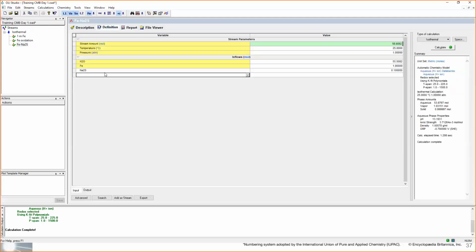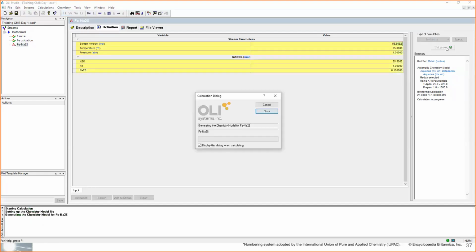So what about if we turn on the oxidation state for sulfur, all of them? What happens? What can happen? So we go to the redox, and then we click on this drop-down arrow, and we click on sulfur. Just enable it. So now we have both iron and sulfur, okay? And then we recalculate. So again, I just use the drop-down arrow and simply click on the sulfur to make sure that it's selected, and then click calculate.